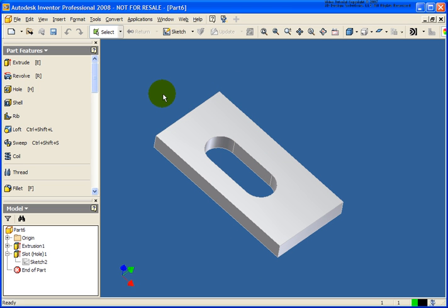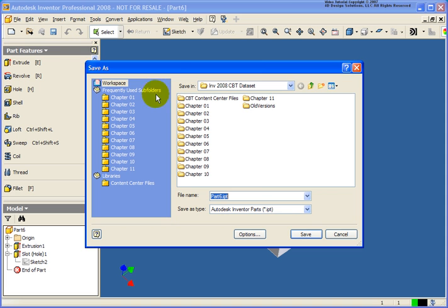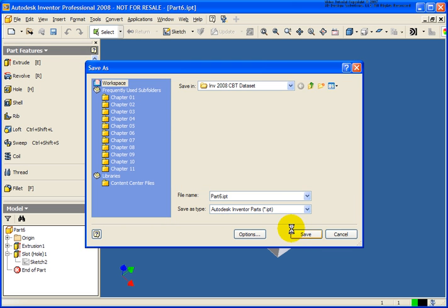So next, what I'd like to point out is that we can go back and publish features to a library as well. But before you go back and publish a feature, what you do need to do from the Autodesk Data Management Server console, you need to go back and add a library that you can go back and place content into. The default libraries are read-only and you will not be able to publish your content. But once you do have your content ready to be published, the first thing I'll do in this case is I'm going to save the file. I'll just keep the default.